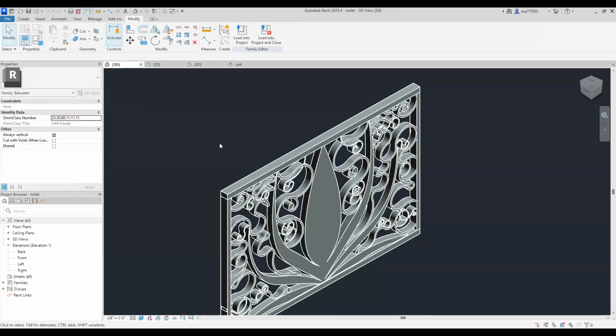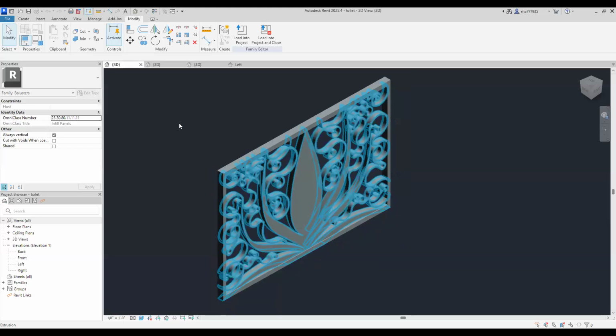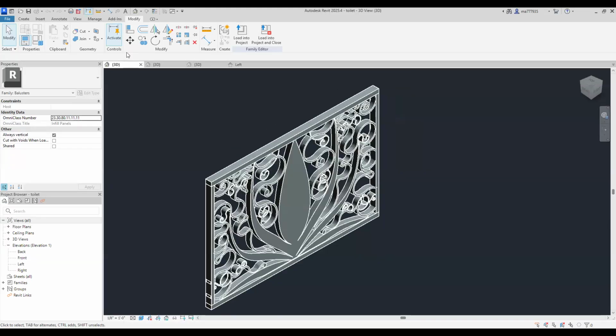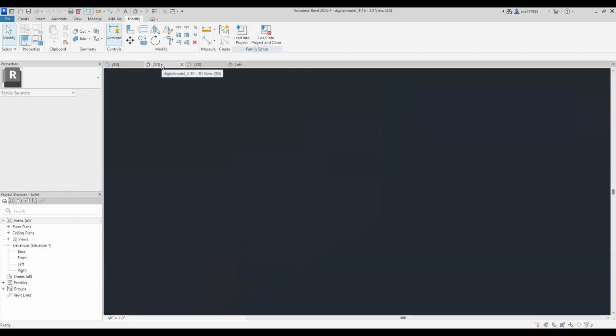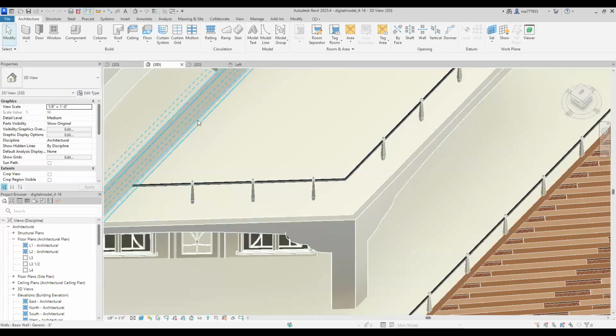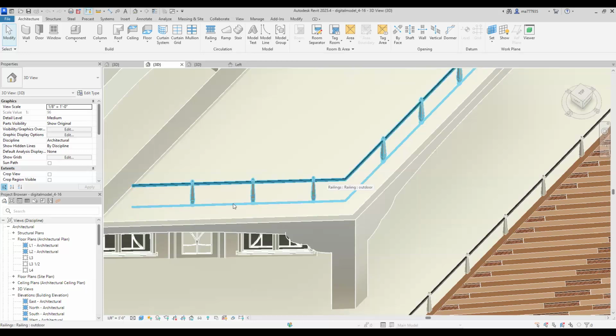So what you're going to have to do, unfortunately, and this is what I was trying to explain in this video, is each one of these railings or panels, you'll have to export as a DWG, import into a family, trace them in that family, and make a family panel, which is different than a railing panel, right? The rest of my video will explain how to make those.